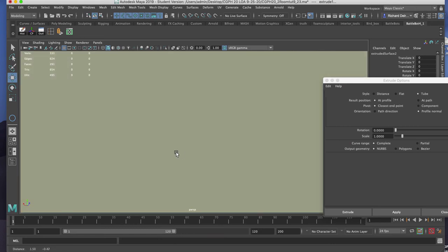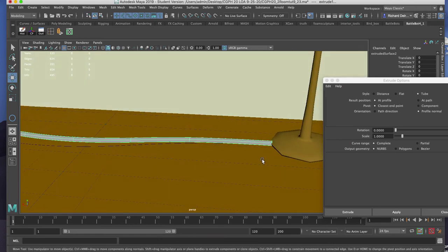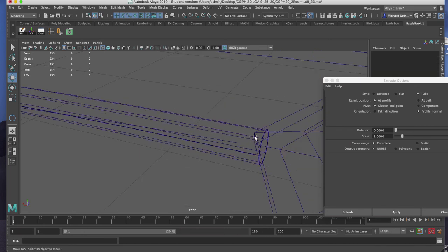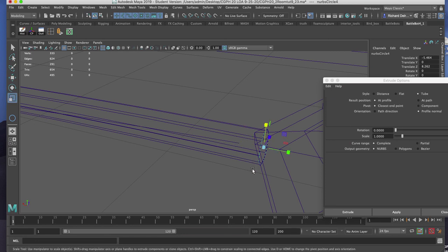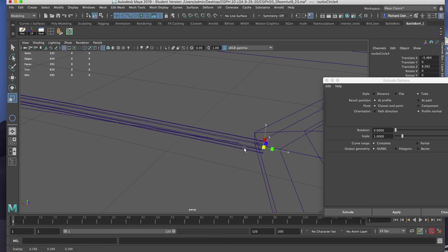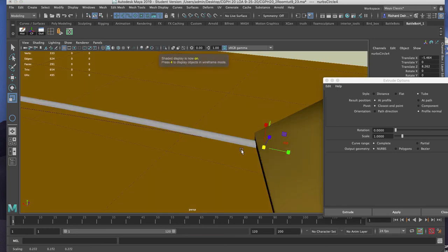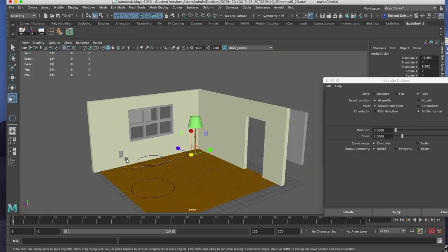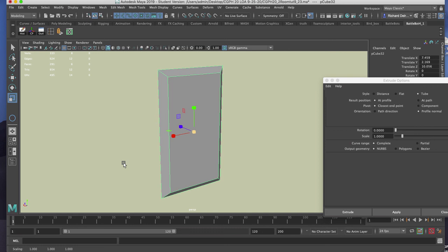To do so, I need to select that little circle that we used to generate the wire with the path. So I'll zoom in, select the little circle, hit R on the keyboard, and I'll start to drag to the left to make it thinner. And again, this is very subjective, so I've got something like this at the moment. Now I'm going to address the end where the outlet is.